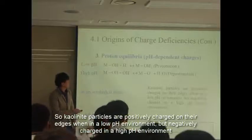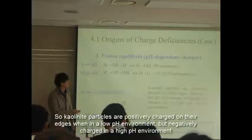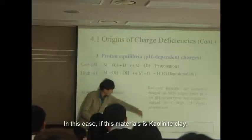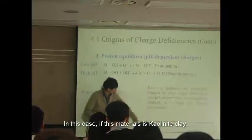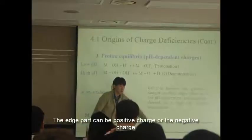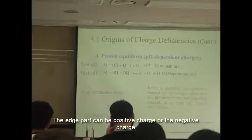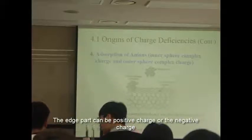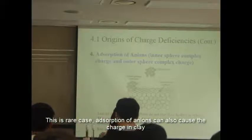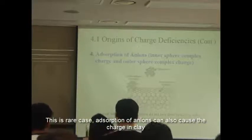In case of kaolinite, the particle can be positively charged on the edge when it's in a low pH environment, but negatively charged in a high pH environment. So let's say this is the kaolinite clay, the edge part especially can be positively or negatively charged. And this is a rare case, but the adsorption of anion can also cause the charge deficiency of clay.